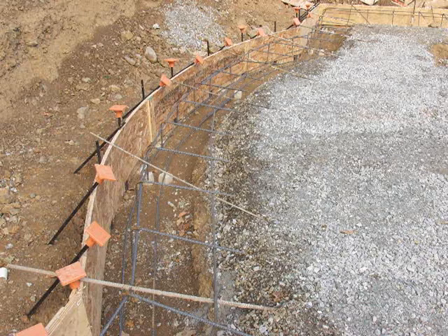Finally, you'll have to run the rebar in this curved section. Now you could use the rebar bender to curve it as nicely as possible, but it's really not that important. As long as you have the rebar basically in the shape that you want, that's all that matters. So we come in here with a straight piece and just bend it against our knee as we move around that curve, which gives us close enough. It's never going to be seen. As long as we keep it away from the edge, it'll be structurally sound.